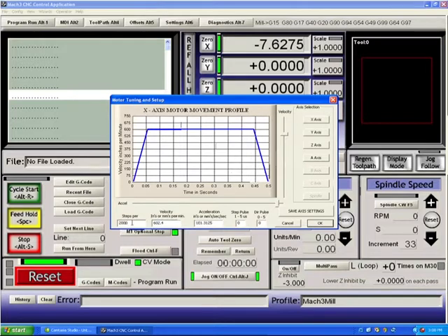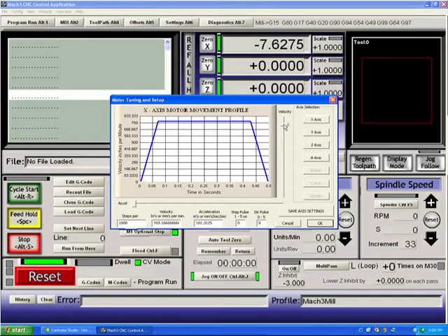Once you've set a steps per millimeter of 2,000, you need to test to see what acceleration and what velocity you're going to use. I should mention that before you start anything on this tab, hit the axis button that you're interested in. It brings up the stored results of that axis. So here we have the x-axis. We're going to set this as an example for the user to 1800 steps per millimeter. Anytime we change this steps per unit, we must touch the velocity and touch the acceleration sliders so that the system will recalculate its current settings based on its steps per unit.